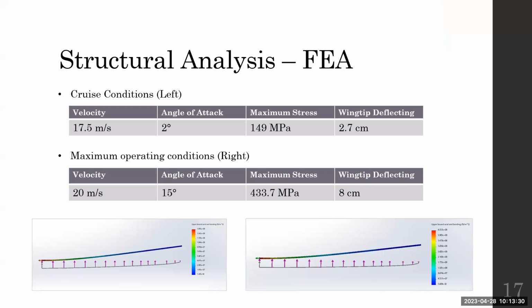And this is the flexion of just the spar itself. Do you consider the stiffness that the skin and the ribs add as well, or is it just the spar alone? No, for the FEA, I just assumed the 3D printed parts weren't there. That was kind of a built-in factor of safety for us. We knew the epoxy and 3D printed material are going to be extremely strong and add a lot of stiffness, so it is a little factor of safety built in.